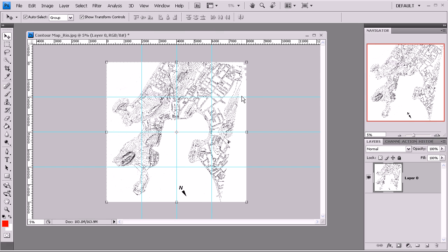Right, so what this is showing us right now is how our site mesh is going to be split up. The reason why we're splitting it up is for 2 reasons. First of all, it allows our texture sizes to be much smaller if you don't have 32 or 64 gigs of RAM to run the model. And second of all, it allows our site mesh in each case to be slightly smaller. It means that you can have more polys and smaller objects to work with. It's just a way that I like to optimize things to keep each object in the scene relatively small.